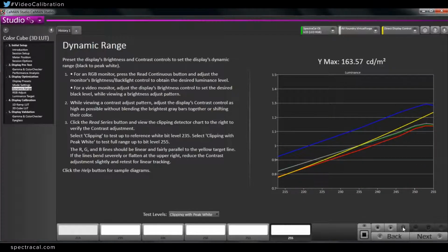It's much higher than the green and the red reading. Can you just explain it? Is that something that we should be concerned about, or is that something that's acceptable for doing this test? Yeah, so essentially, if this display was theoretically perfectly calibrated, the red, green, and blue lines would all be right on top of each other. Right here, this tells us that there's too much blue in the white point.